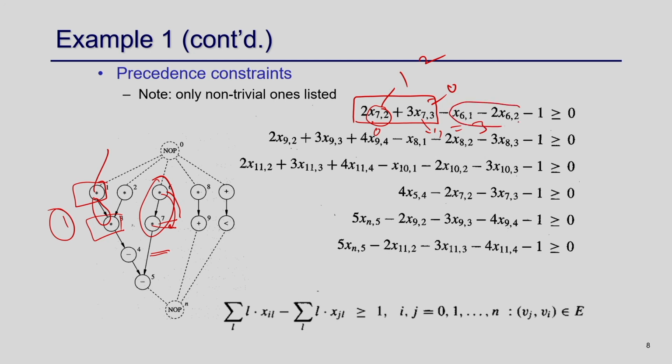And this is actually given the start time of the node 6. It is either in timestamp 1 or timestamp 2, and it is the delay of the node 7. So, the start time of 7 must be the start time of this node plus 1, right. This is what this expression says. Now I have to take each such edge and represent them using the constraint. And the only difference from the generic case is that here, in the previous case it was D6, here it is just 1, right. That is the only difference from the generic case.